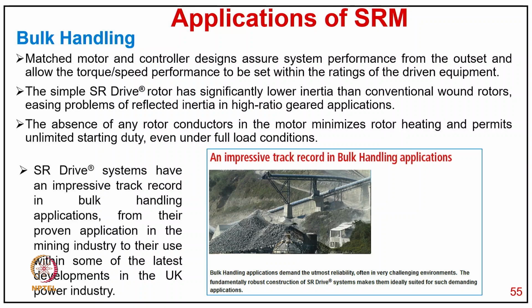Now it's for bulk handling. As you can see, the photograph for bulk handling of different kinds of material, let's say cement. So matched motor and controller designs assure the system performs from the outset and allow the torque performance to be set within the range of the driven equipment. And the simple SR drive rotor has significantly lower inertia than a conventional wound rotor, avoiding the problem of reflected inertia in a high speed, high ratio geared application. The absence of any rotor conductor minimizes rotor heat and permits unlimited starting duty even under full load conditions.